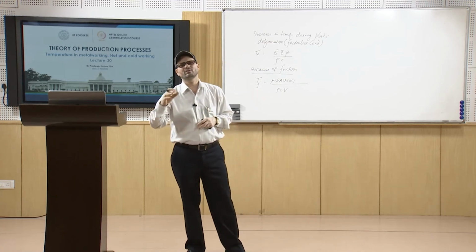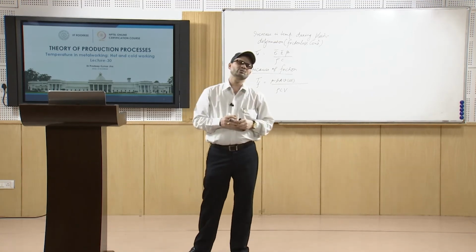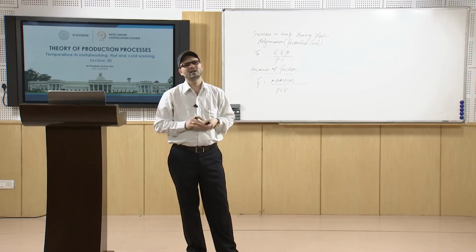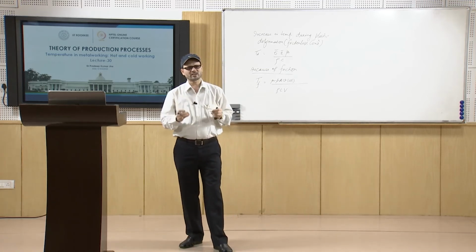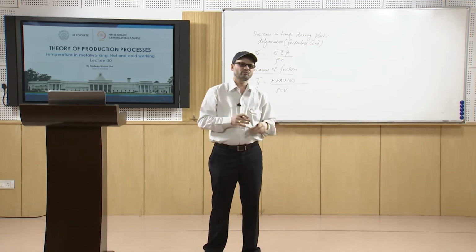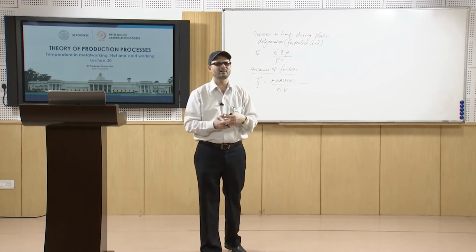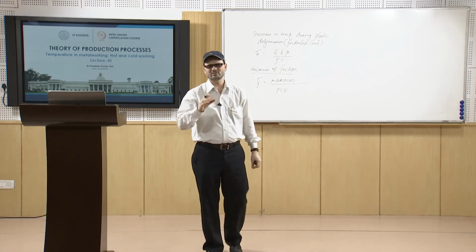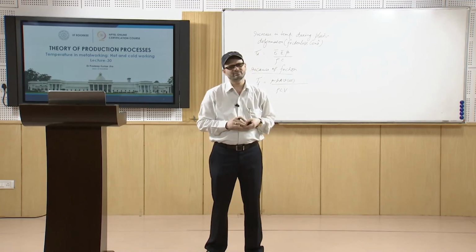So, when it is going for one pass, in the second pass you have to ensure that if there has been surface reactions or formation of oxides, then these oxides must be removed. Otherwise, the oxides at the surface may be rolled in between the die and the surface of the metal, and that may leave a dent mark on the surface of the material. So, that may decrease the surface finish of the material.